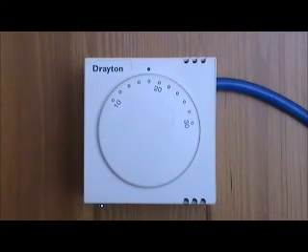Turning a room thermostat to a lower setting will result in the room being controlled at a lower temperature, and it saves energy. The heating system will not work if a time switch or programmer has switched it off. The way to set and use your room thermostat is to find the lowest temperature setting that you are comfortable with and then leave it alone to do its job.